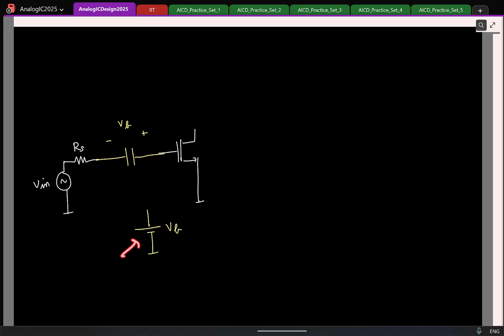right? And of course you have to make sure that the capacitor is charged to that required VB. I have the grounded voltage source VB. What do you do? Yeah, can I connect it directly like this? Why not? Then the voltage across the gate will be fixed to VB. That's exactly the opposite of what you wanted. So you put a large resistor RB here and couple. And let's say here I have the PMOS transistor connected to some bias voltage acting like a current source.